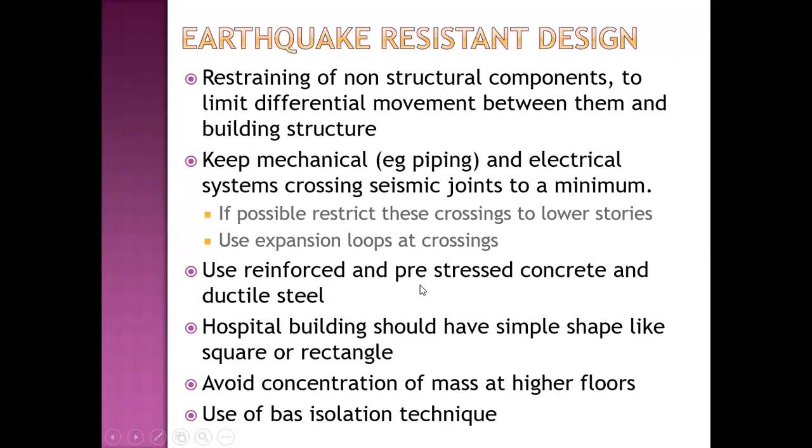Use reinforced and pre-stressed concrete and ductile steel. Hospital building should have simple shape like square or rectangle. We should avoid concentration of mass at higher floors and use base isolation technique.